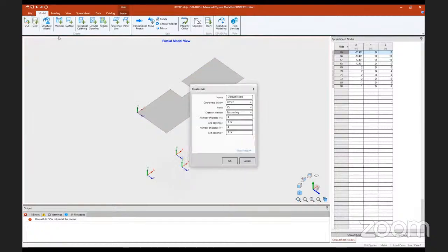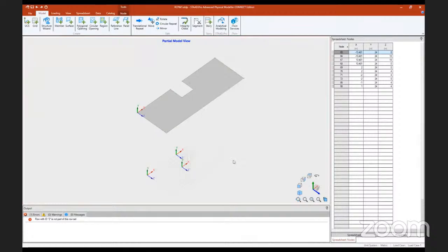And then go to the grid. So this is going to be 3. Again, the plane is going to be the XZ. So the number of spaces in the X direction, I'm going to go 20 and 10, let's change that, XZ. So in the X direction, we've got 20, the 1 meter, and Z direction, so I'll click on OK there. So we now have the grid appearing up here. So select that.